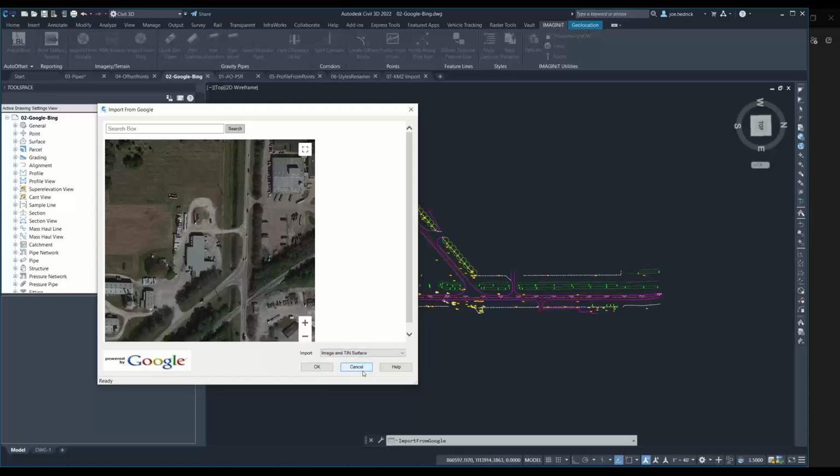Right? I like to point out that Autodesk brought back some imagery. They implemented live maps, and it uses Bing. And for some people that works just fine. For others they prefer Google. And this is an option, but the one thing that never did come back was the import from Google Earth, the old legacy routine. It could also import terrain information, right? So we're able to hook into that terrain information as well with this.